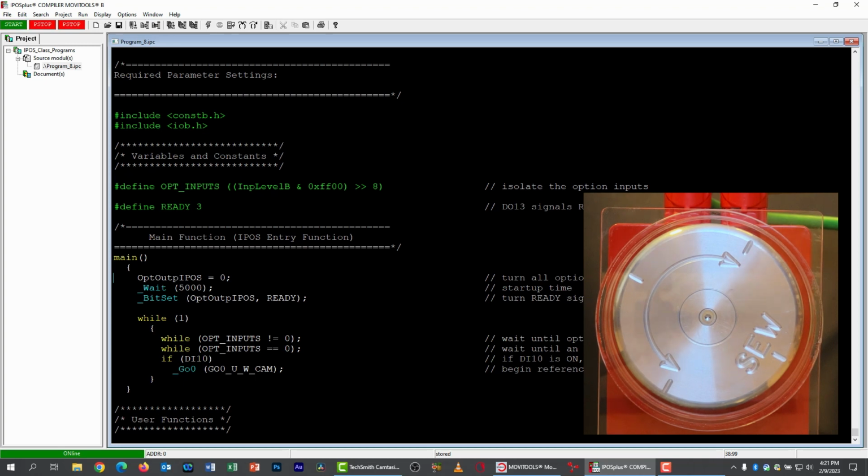You can see, therefore, if I trigger my right limit switch when I'm supposed to be moving left, the VFD definitely doesn't like that. It thinks something really weird is going on because that's not even a limit switch you should be able to trip, all things being normal. Let's start referencing again and trigger our other limit switch, the one on the left side.